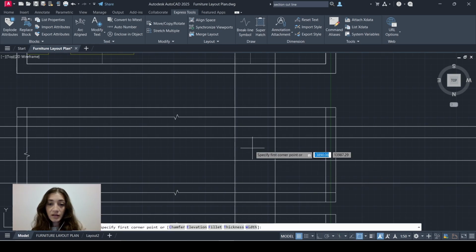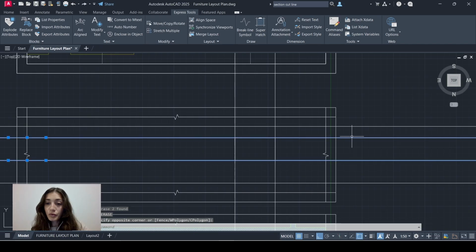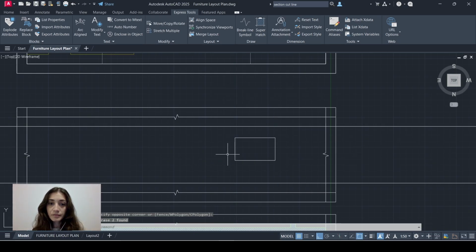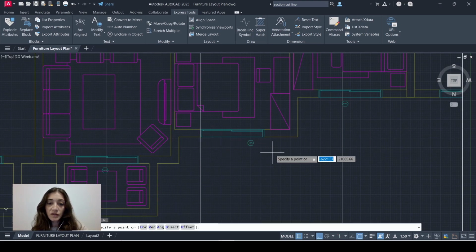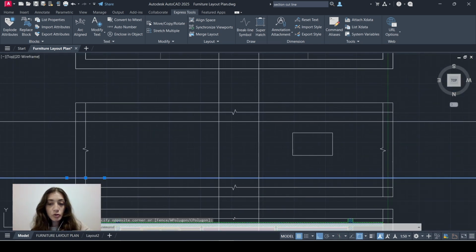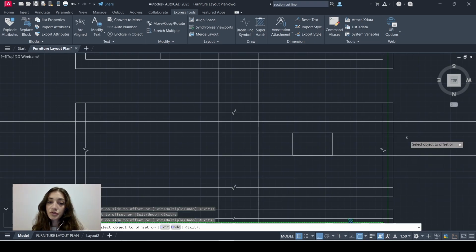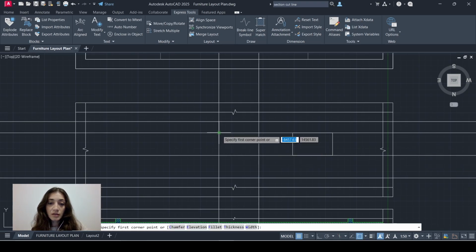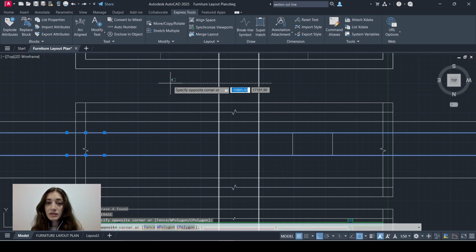And I'll draw a rectangle over the space that was defined by those construction lines. Now I can remove those to make it easy on the eyes. I'll do the same thing for this window, which is the secondary bedroom window. So XL, draw it here, and one on the other side. And the windowsill here is also at 120 centimeters. And the window is also 120 centimeters high. And I'll draw the rectangle over the space that was formed here. And I'll remove the construction lines.